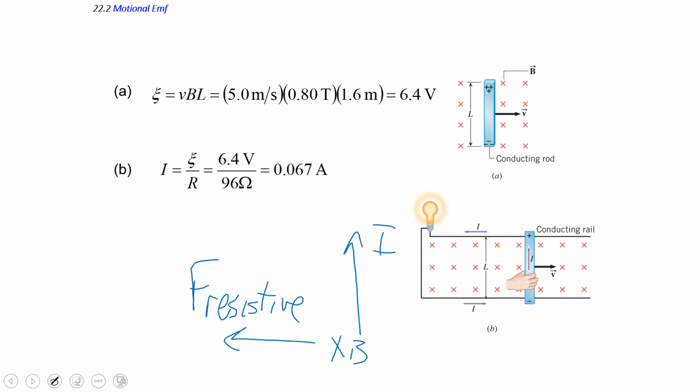The circuit's whole design is that without a source of energy, it comes to a stop. If the current naturally flowed, say the bar shifted a little bit for some reason, and the electrons in it drifted to the right, then it would be pushed upwards a little bit. That would cause the electrons to drift left from this resistive force. The bar wants to stay stationary. You have to do work to move it.